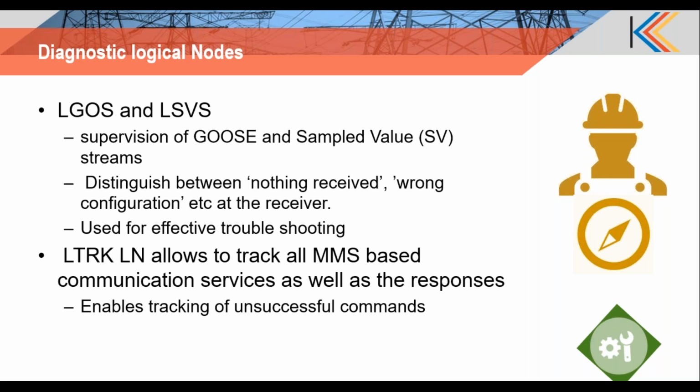Instead, there will be only one instance of that logical node, and there will be multiple CDC instances representing each of the MMS services. So if you have a report control block, and when an external client enables that report control block, automatically that will be updated as an entry, or there is a status field in your LTRK logical node which says that, yeah, there was a request from so and so client at so and so time for enabling the report control